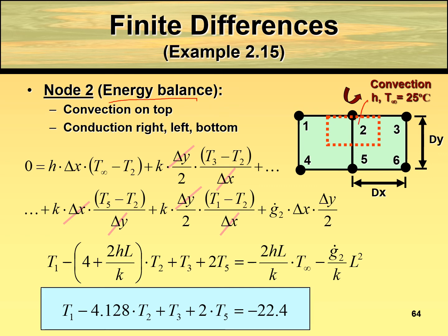So we have convection coming in here, and conduction coming in here, here, and here. For convection again, h, our A is based on this. Imagine this as another surface. B is 1, so times 1, right? So this entire thing is delta x. And then because heat is coming in here, T infinity minus T2. So that is done. And then from here to here is conduction.